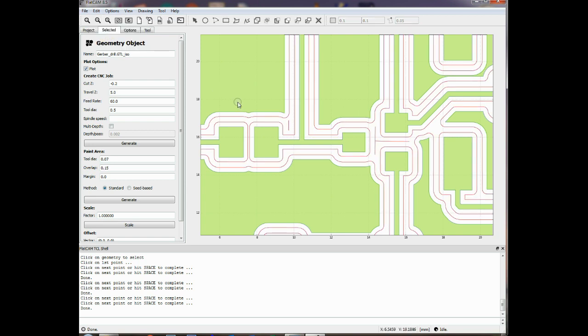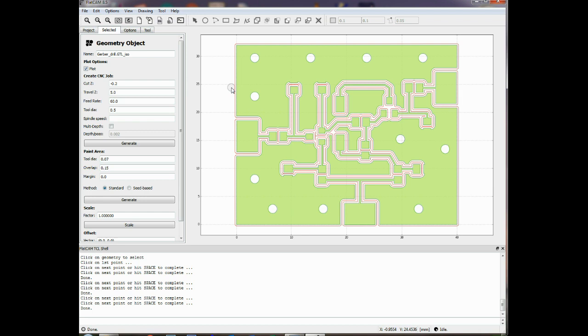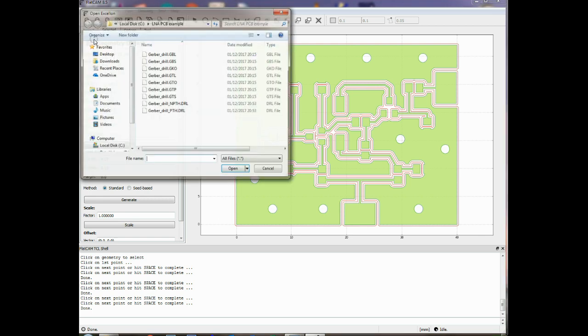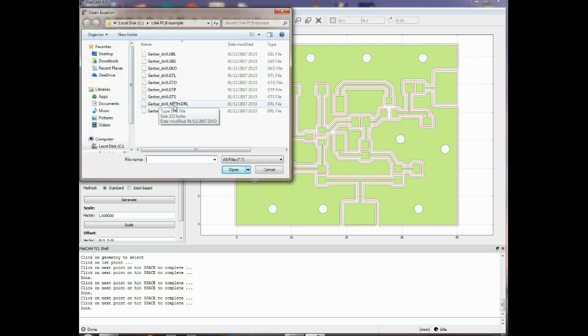Right, zoom it out. Now the next thing I needed to have a little post-process fiddle with was the CNC hole drilling file. It's again easier to just demonstrate. So if I open up, it's not a Gerber file. It's an Excellon file. I have trouble pronouncing that. An Excellon file, which is this npth.drill file here, which is also exported from Easy EDA.